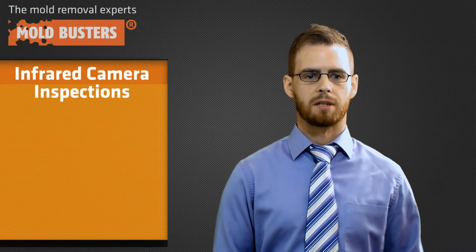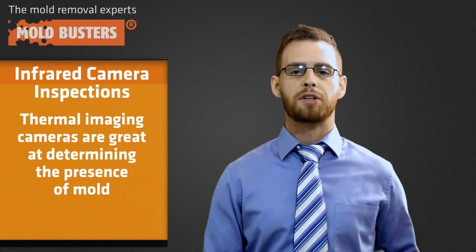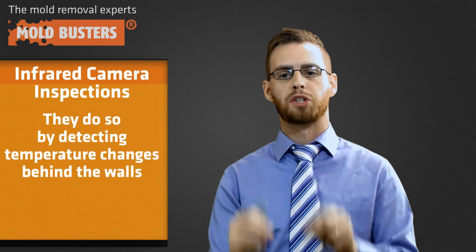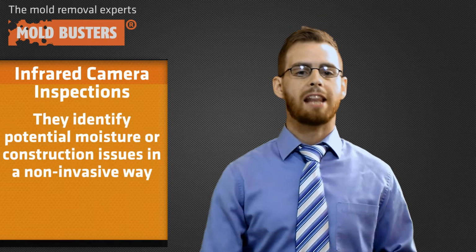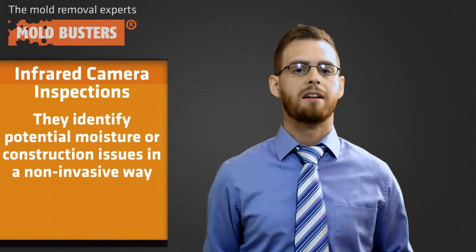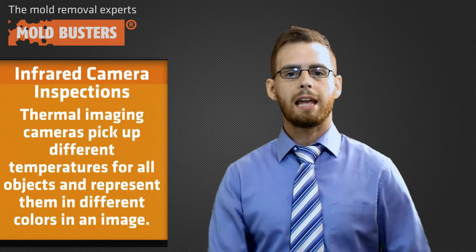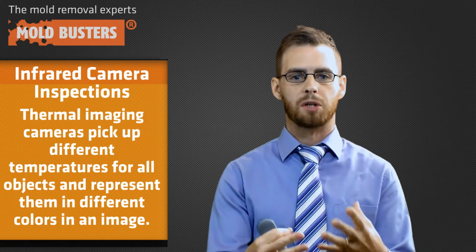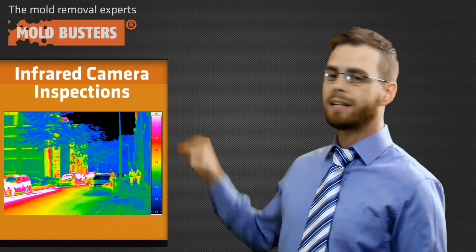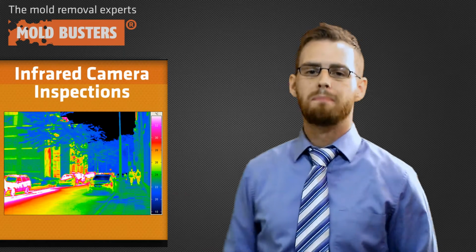Infrared camera inspections. Thermal imaging or thermographic cameras are great at determining the presence of mold. They determine the presence of mold by detecting temperature changes behind the walls, and they identify moisture problems and other construction issues in a non-invasive way. Now, all objects emit heat. Infrared cameras pick up different temperatures and represent them as different colors in an image. For example, white equals hot, blue equals cold, and red equals medium heat.